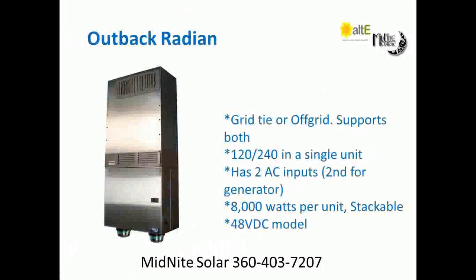It will AC couple, but when it's AC coupled, any of the Outback inverters need a way to disconnect the grid tie inverter from the utility grid. What happens in AC coupled is the grid tie inverter will push against the output of the battery-based inverter and physically make it run backwards and charge the batteries. There's no problem with that at all, except some of the battery-based inverters, like the Outback inverters, don't regulate in reverse. Therefore, they will just keep charging, forever.